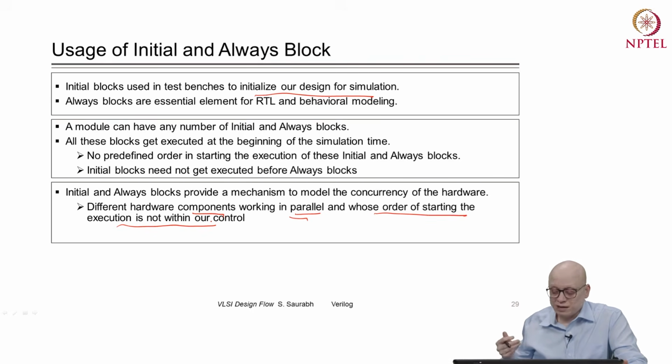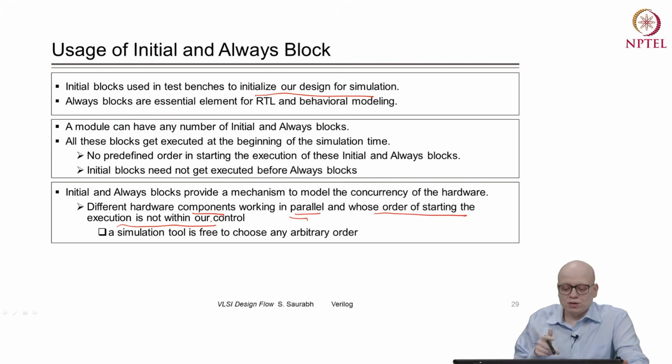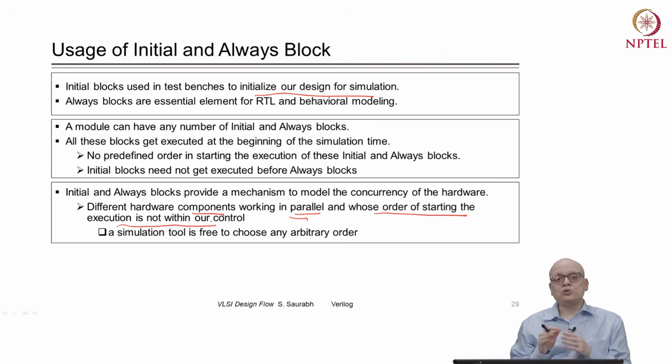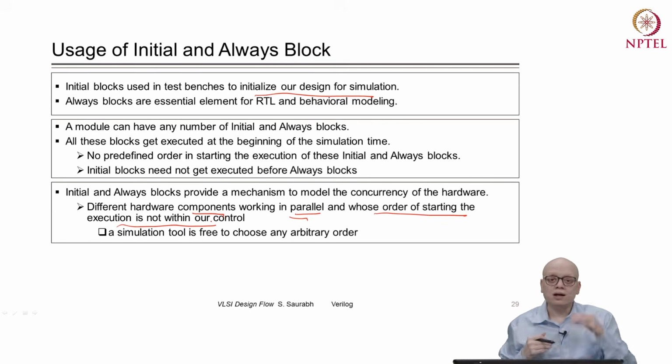This is important because the simulation tool is free to choose any order. So, we should ensure that by choosing any order of execution we get the correct result. The result should not depend on the order of execution of the always blocks in a given Verilog module.